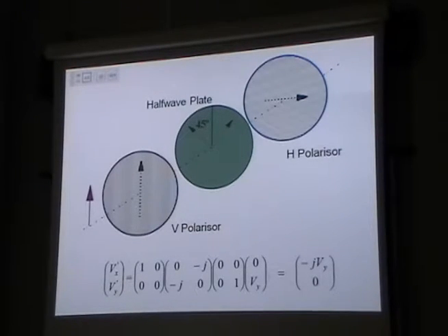And that's what your display does. Every time you put your display on, there's a nice white background. What you have is a pair of cross polarizers. You have a liquid crystal in this particular geometry here, so it's providing a 45-degree rotated half wave plate. And lo and behold, we're getting all the light through the system in a really nice bright state.